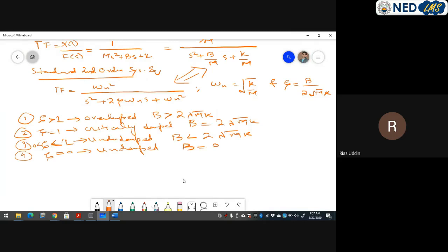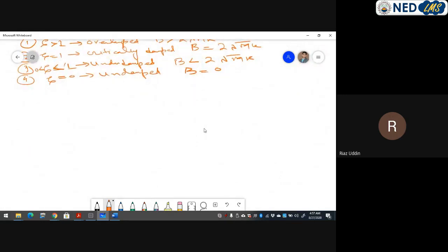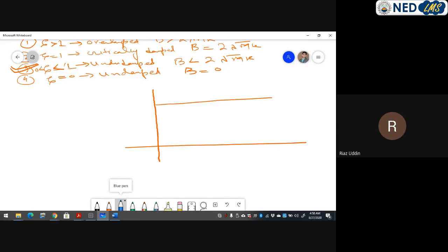So in this lab, what you have to do is get the time domain specifications of a second order system. So what does that mean? In the second order system, we will be selecting the underdamped case. Why are we having the experiment of this case specifically? Because this is the fastest of all the cases. That is why we have chosen only the underdamped case. Let me highlight it so that you can remember it. It means we will be choosing the value of ζ between 0 and 1.